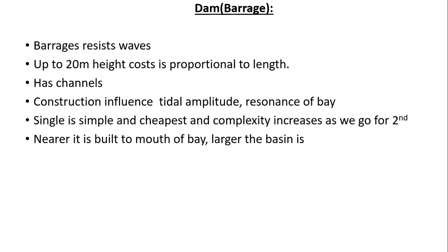Okay, so if you go for more than one basin, the complexity increases. More complex schemes will involve generation on both ebb and flow tides, or the construction of a secondary basin that will permit water to be stored and discharged whenever desired. This is somewhat complex, but it will provide more firm power on a flexible basis. Expertise is necessary to design and build such structures.